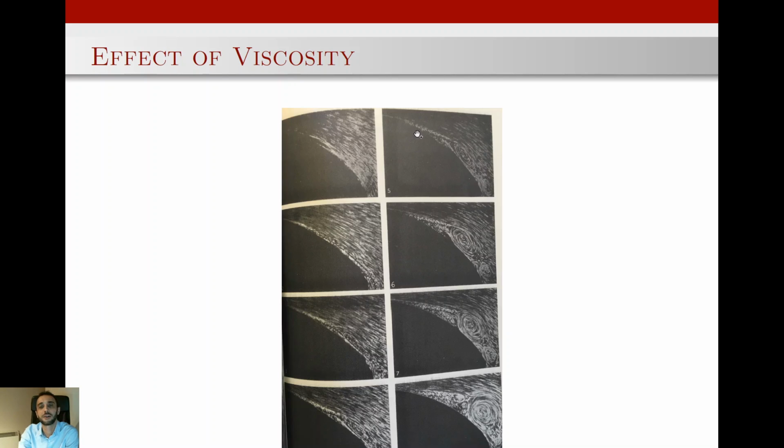Then if the Reynolds number increases, we will have vortices formed, and that's a balance between inertia and viscous terms that creates these vortices. And if the Reynolds number increases to an even larger value, there will be instability, and these vortices cannot be held in place, and they start shedding, separating from the object, and create the vortex streets and the wake region.